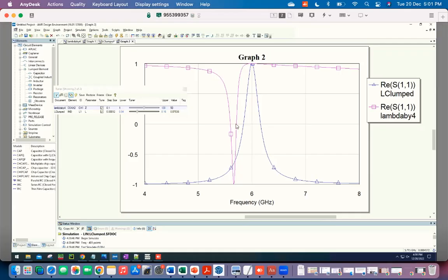In this picture, that's still considered fairly low, because the Q factor here would be about 100 megahertz over 6,000 megahertz, so it's like 60. That's not a very high Q. Usually people are trying to make Qs of 1 million and higher for the kind of applications one is using, or at least a few thousand or a few hundred.